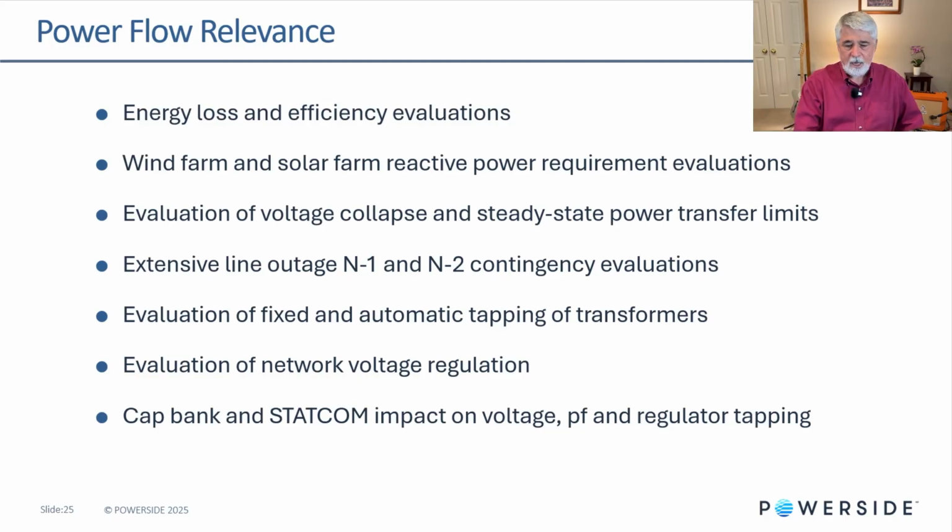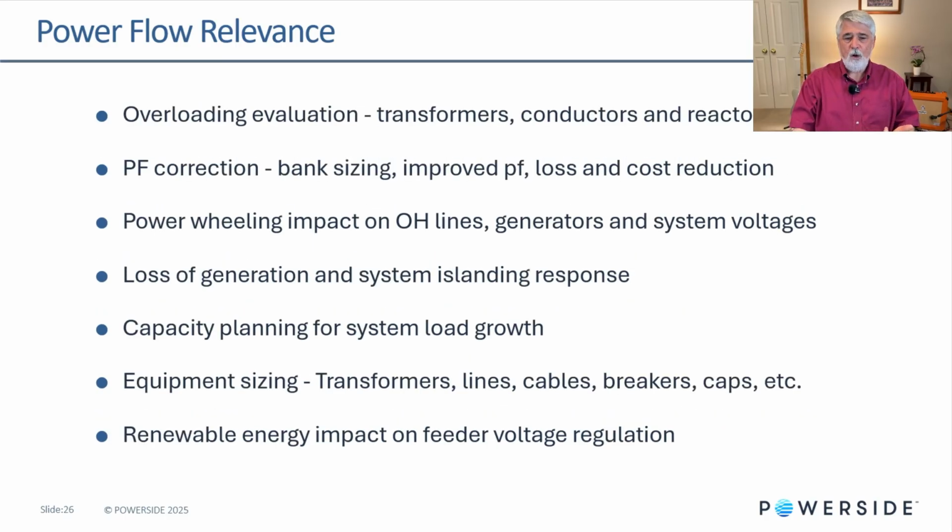Cap bank and STATCOM impacts on voltage, power factor, and regulator tapping. This one here is really critical for distribution feeders, especially today with a lot of introduction of solar sites on distribution feeders, where the generation back into the feeder causes a voltage rise. And this happens repeatedly, day after day, causing possibly excessive regulator tapping. If you want to simulate and know those conditions, you can use a power flow.